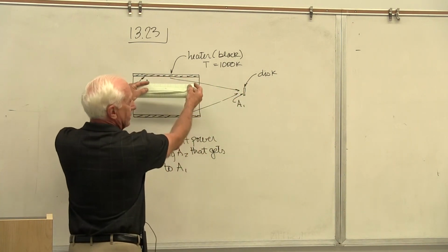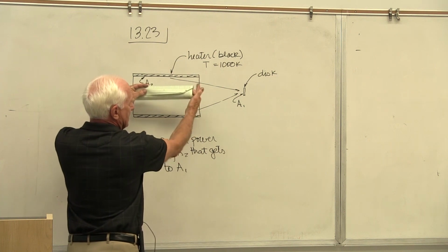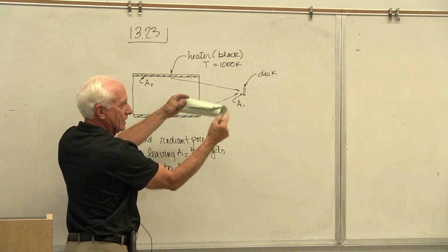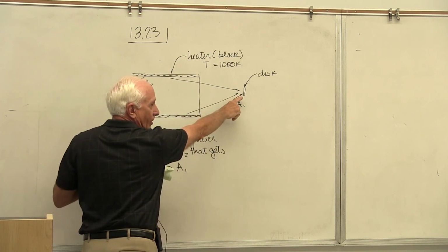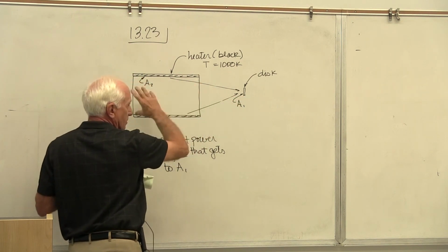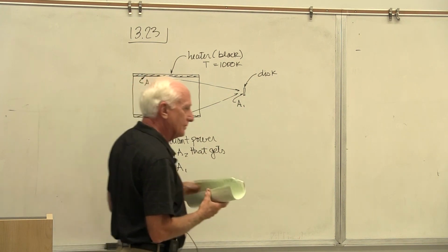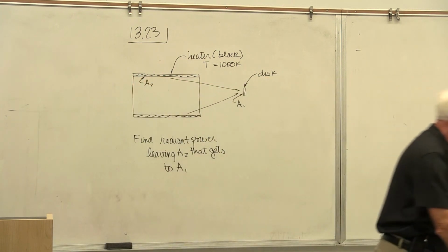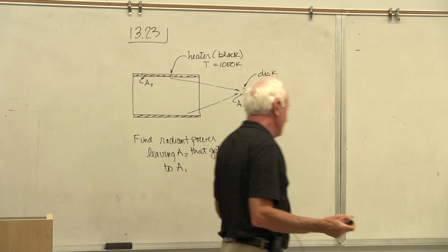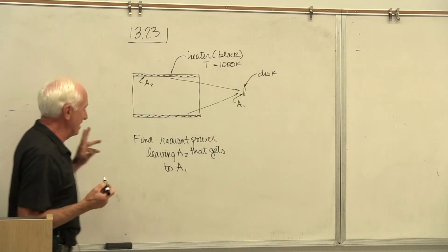Here's a circular heater like that. You heat the inside surface. Some radiation gets out that hole and strikes that small little quadrant. This is a tube. That's a little surface, a diameter quadrant there. I don't want the net exchange. I don't want Q12. I want this in words. Is there a shorthand notation for it?